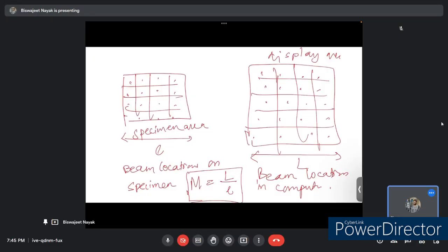Now whatever information we are getting in an SEM image is conveyed when a contrast in the backscattered or the secondary electron signals is created, and this contrast is created by differences in the interaction of beam electrons between a specimen feature and its surrounding.